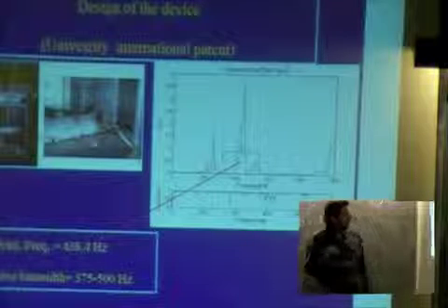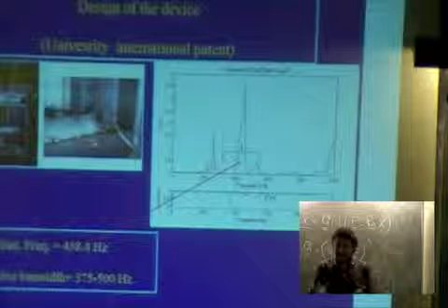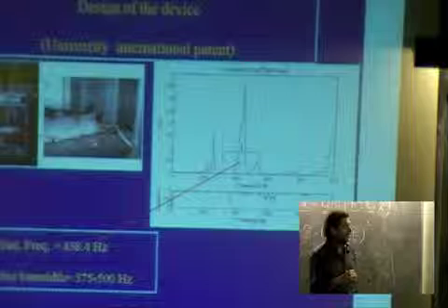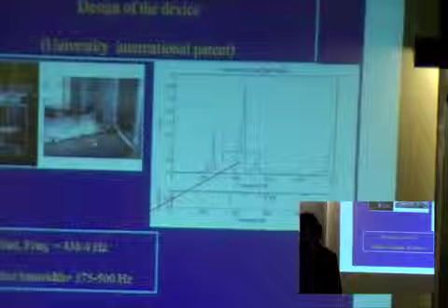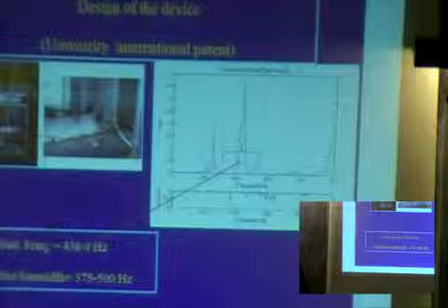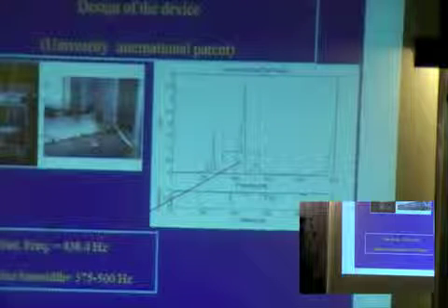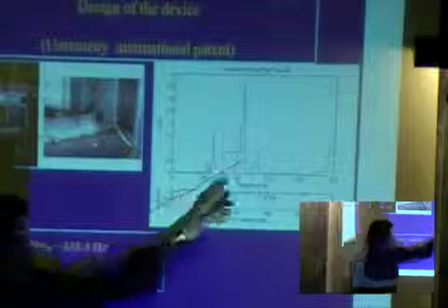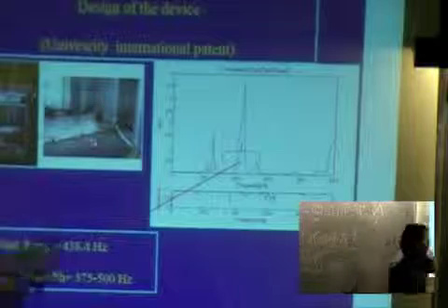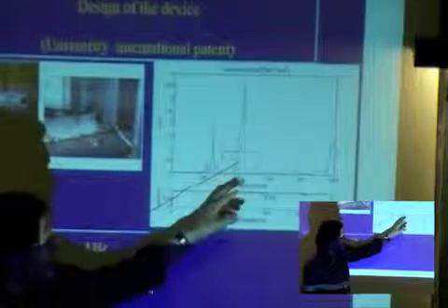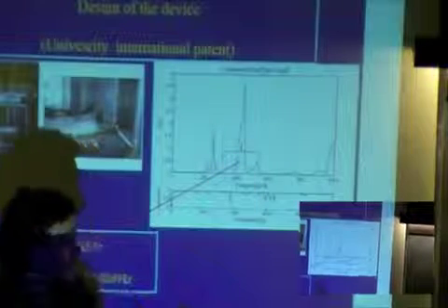The first step is to determine some properties of the environment, through experimental identification of some property of the system that is attached to the box. We made some preliminary measurements, and we identified a sharp peak at some frequencies. Of course, this is an experimental result. You have a very sharp peak in the region between 300 Hz and 500 Hz, more or less.